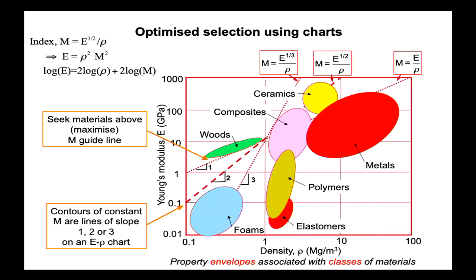But what these lines provide us with, for axial tension, bending of a beam or bending of a plate, which is the limit of what I'm worried about for right now, is the potential to have a limiting line. That is, instead of equals, we can have one side of the line or the other side of the line, depending on less than or greater than, the inequality I've been talking about. And that's rather nice. In this case, if we want to maximise stuff, we want to look at materials above the line. Minimise, of course, could be anything below the line.